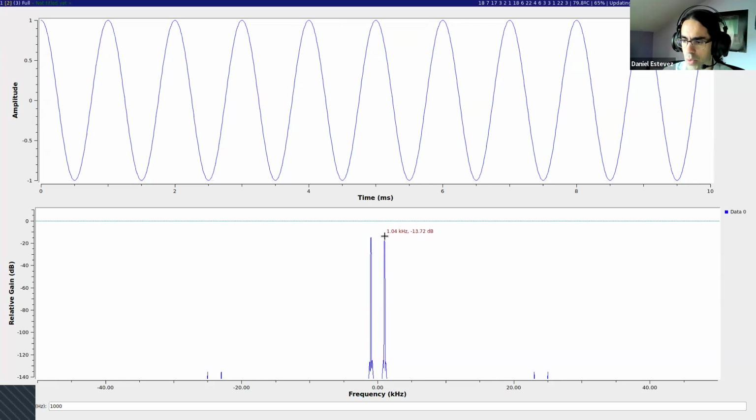And then we get a positive frequency, but since formally the Fourier transform has negative and positive frequencies as the output, we also get the same thing in a negative frequency. Somehow, you can also think someone could say the period here is -1 millisecond if they counted from here to there. It's like going 1 millisecond backwards in time. And that might also be a sensible way to put it.